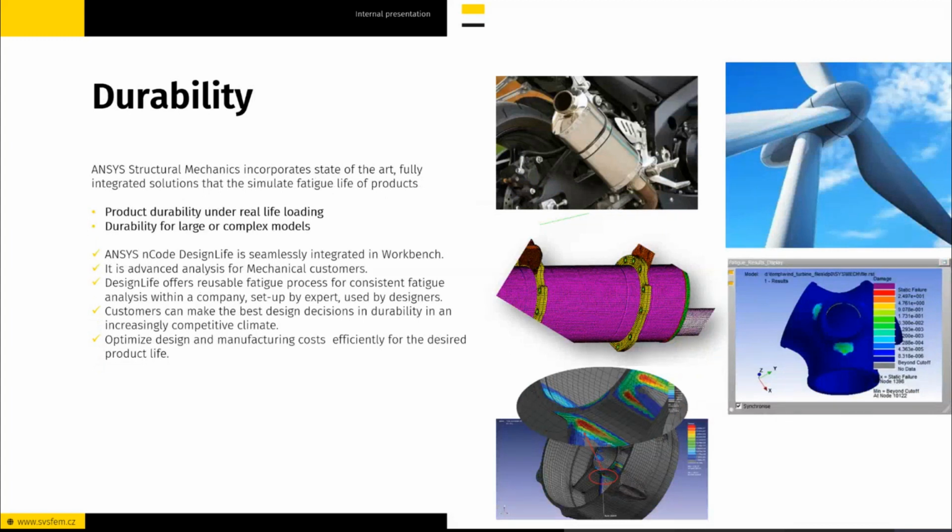If you are able to describe the base physical response, you can try to compute also derived variables. It's very often durability or product life. And it can be simple for simple geometry. But when you combine coupled physical loads together with a large and complex model, it's difficult to find the weakest part which will lead to damage or to failure at least. For example, when you are solving wind turbines, you have strongly coupled tasks with structural, thermal, fluid, and electromagnetic effects, and revealing the fatigue life and prediction of product life can be really a challenge.